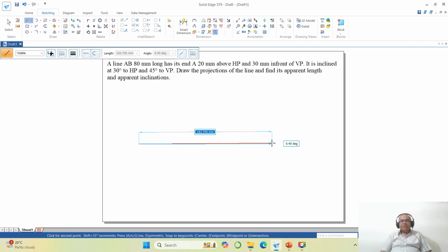Here, it becomes very difficult for me to get to the exact point. So I want 0 degree, so you just click on this. Now if you try to do that, you can see that the horizontal bar is coming, which means it will take exactly 0. So you take some distance and click. Okay. Then you just right click.